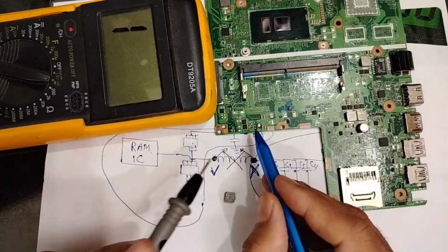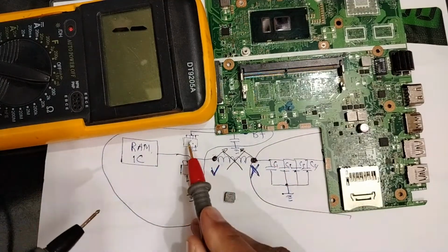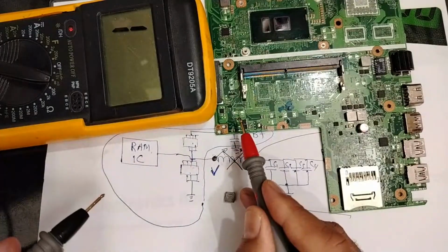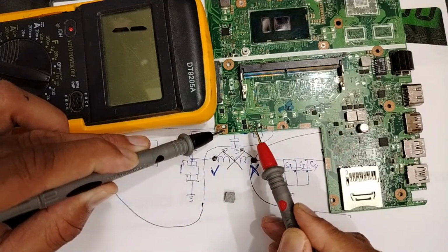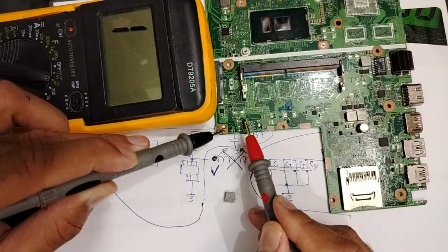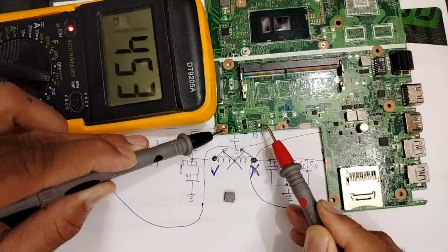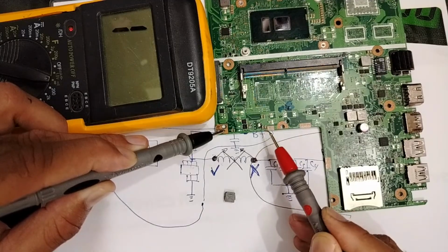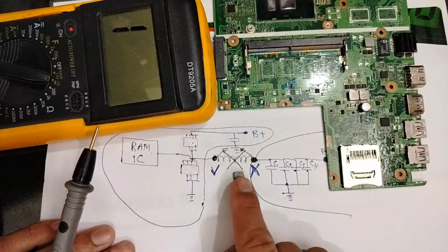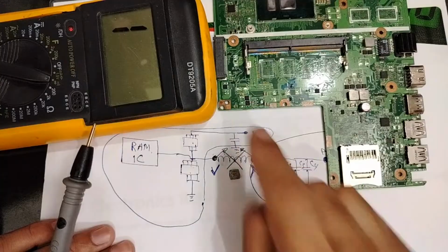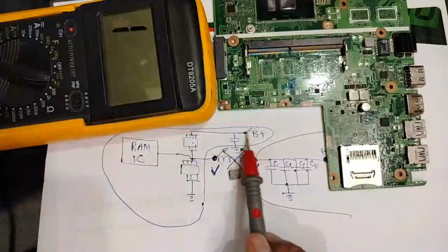Look. Okay. Here means MOSFETs, IC, everything, even this ceramic capacitor, no short. Look, the short is gone here, here no short, no short, everywhere no short. But in this side we have short, here, here, everywhere we have short. Means now we separate the short, my friends. Once we remove the inductor from here, we find that this side is good.